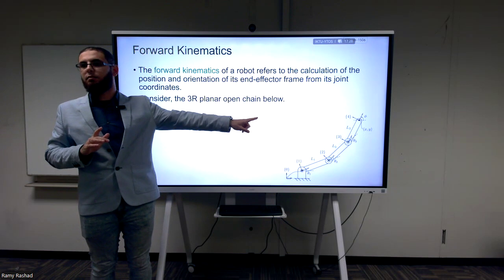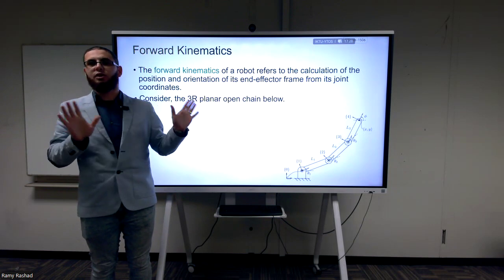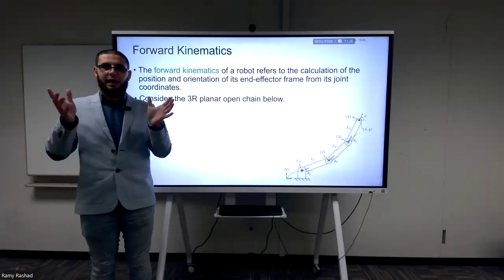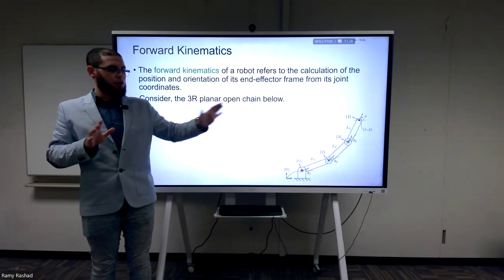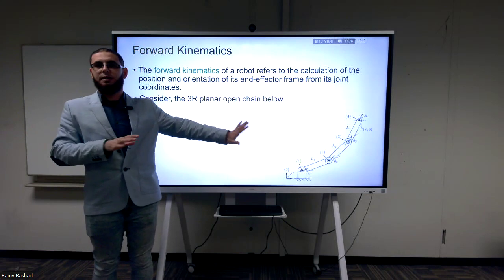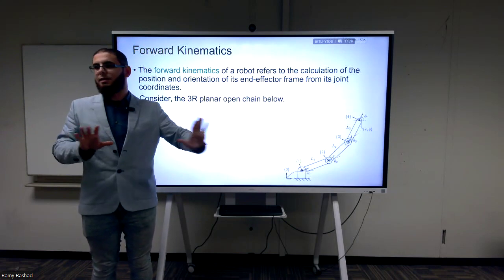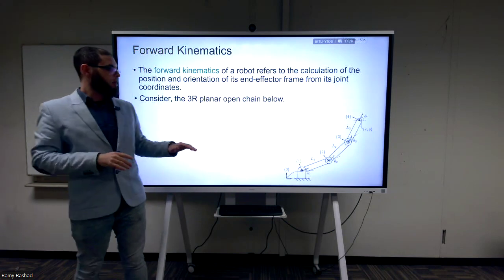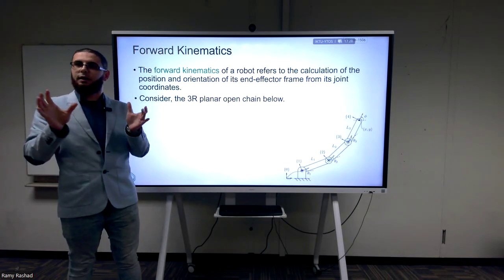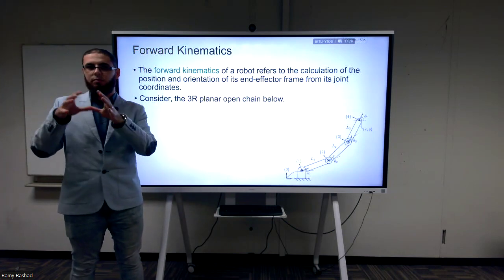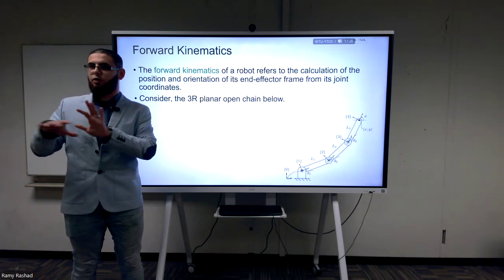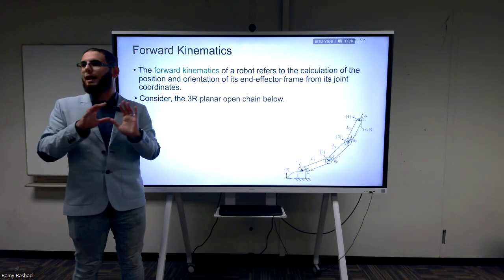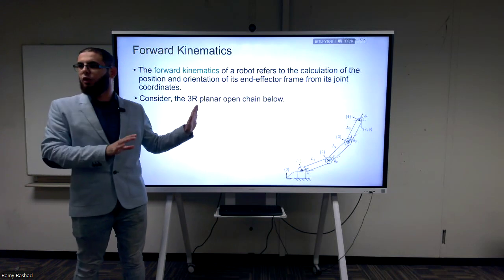In which axis is it? It's in Z, right? So there is no such thing in the end as actually planar motion, because the rotation is always in the third direction. So for simplicity, you can always work with SE3 and you lose nothing. You don't need to define special notation or special math for the 2-dimensional case, which exists, by the way. You can find SE2 and SO2 in some books, but we don't need that in our case.